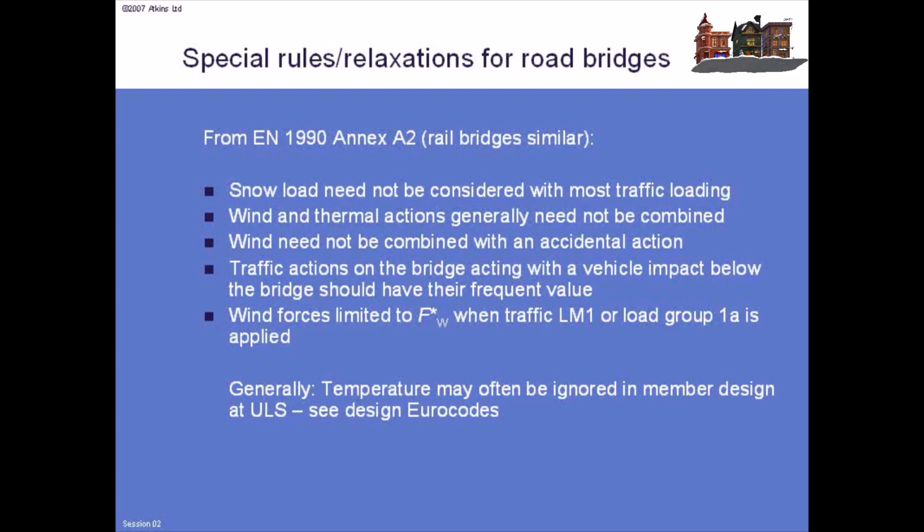You might, in your mind, first of all think, well, when is a ship most likely to impact a structure? Probably when it's very windy. And there's a lot looked at that, and in the end, it was decided no, we'll stick with not combining the two together. And the reason is when you start investigating ship impacts, wind as a cause is actually quite a long way down. Now, the most common cause of ship impact is mechanical failure of steerage. I think the second is the crew being drunk.